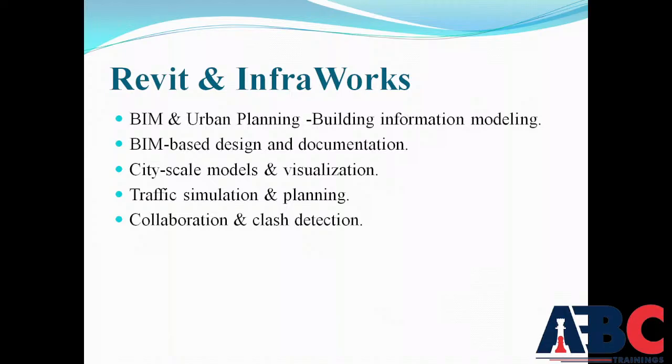Revit creates an intelligent 3D model where components like walls, beams, doors, HVAC, and electrical contain embedded data, such as material, dimensions, quantities, and performance details, giving accurate design representation and automated updates. We can change something in a single view and it will be updated in all views, and we can integrate architecture, structure, and MEP modeling. Next is BIM-based design and documentation.